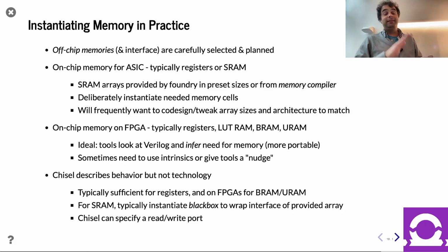Whether you're using DDR, LPDDR, or HBM, or even GDDR, all four of those families of technologies, that's a big change, right? That's not something you just flip the switch on. Now, for some of those interfaces, you have some choices about how wide is the interface, what clock rate, which generation, sure. But for the most part, off-chip memory is not a spur-of-the-moment agile decision, right? This is more of a deliberate, planned out thing.